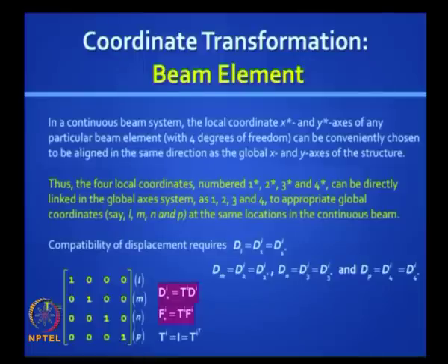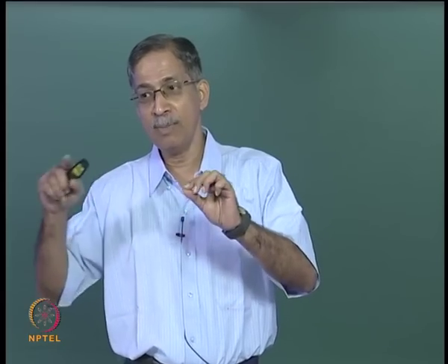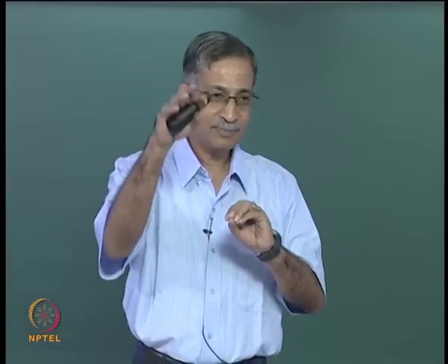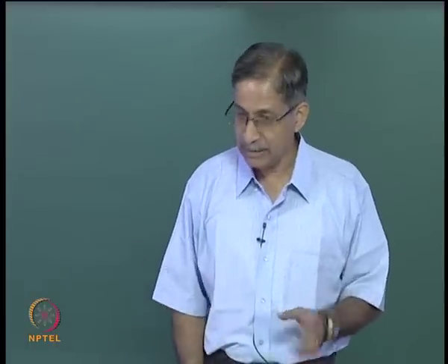Okay. So the beauty about the identity matrix is the transpose of this matrix is also an identity matrix, and so if you try to convert the element stiffness matrix from the local coordinates to the global coordinates, you get back exactly the same matrix, except along with it you will get the linking global coordinates, which is crucial for you to do the slot wise adding. Okay. Is it clear so far?